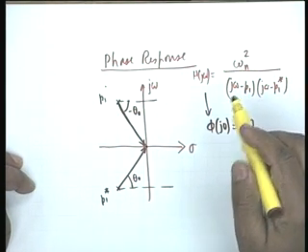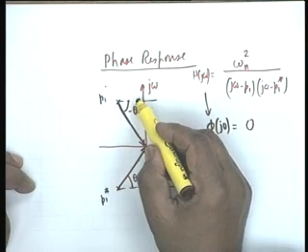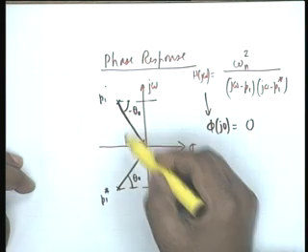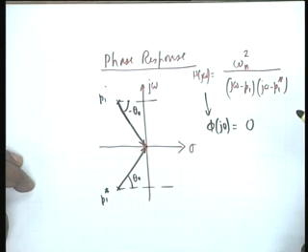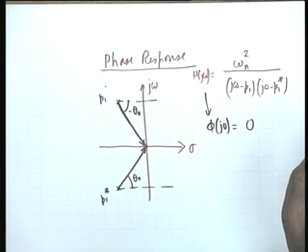But here you see, one of the possibilities was to take this angle, then the sum of the two angles is 2 pi, and therefore the phase would be minus 2 pi. Agreed? Now we are not going beyond 2 pi in any case, between 0 and 2 pi. It could be minus pi to plus pi or 0 to 2 pi, it does not matter. If minus pi comes, we have no other way, we cannot convert it to any other phase. So this phase is 0 or minus 2 pi as the case may be. If you want to extend beyond 2 pi, you are most welcome, it does not make a difference.